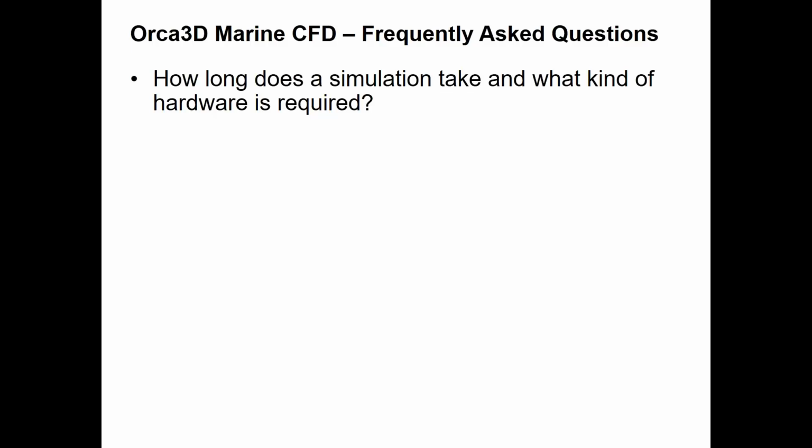In my specific case for this Eastport 32 planing hull, the 25 knot case at 1600 RPM took about 8 to 10 hours to complete. So that gives you an idea of the hardware you need and the times it takes, depending on the nature of the simulation.